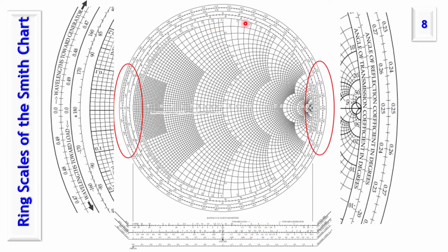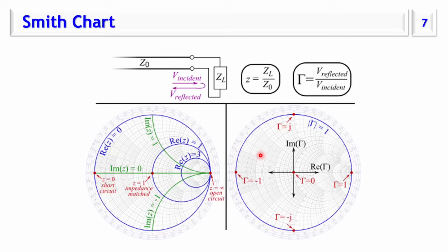And because the reactance can be positive or negative, the center for the reactance circles can be on the positive side or the negative side. So we have those curves here. Those are the arcs, parts of the circles of constant reactance for positive and negative values.